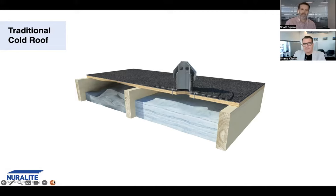But the unintended consequence, which was raised by MBIE, obviously there's less drying potential in that layer. Therefore, the risk of interstitial condensation is just so much greater. And often that's something that can fall by the wayside a wee bit. It's definitely becoming more topical. There's a lot more education, a lot more awareness, which is great.